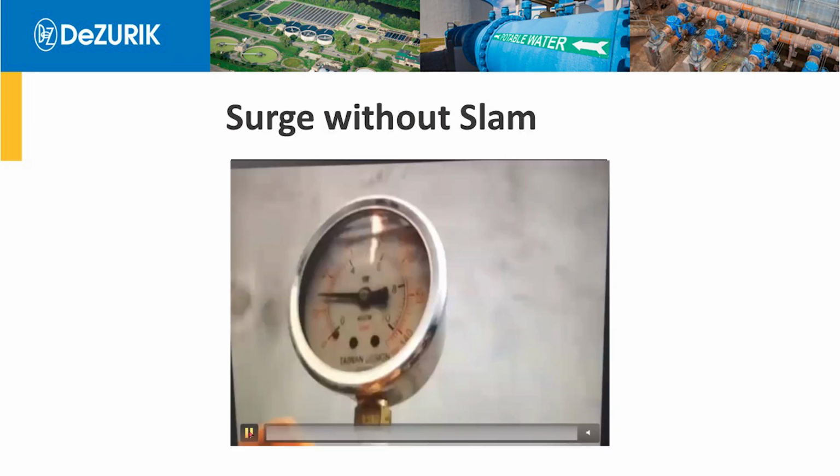Now, when we come to surge and slam, we've showed you that surges are caused by abruptly changing the fluid velocity. Worst case scenario is a pump running and a total loss of power to the system.